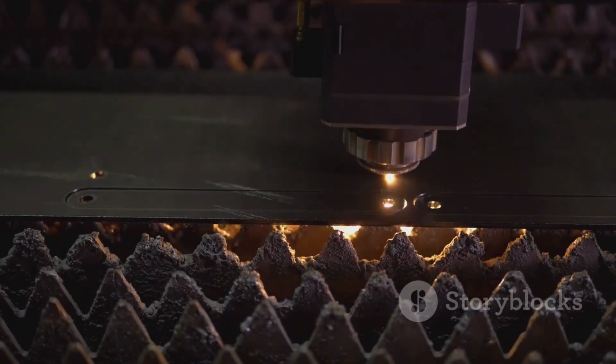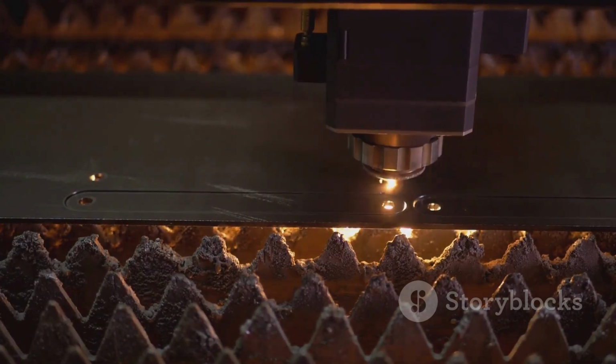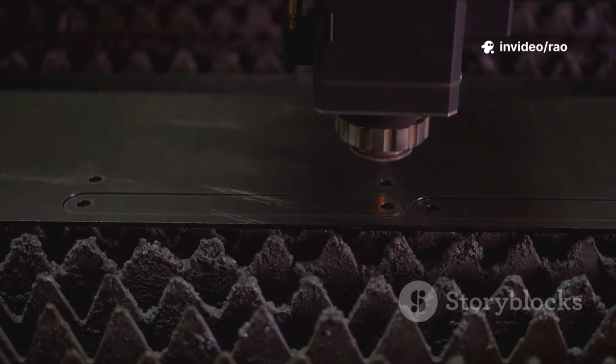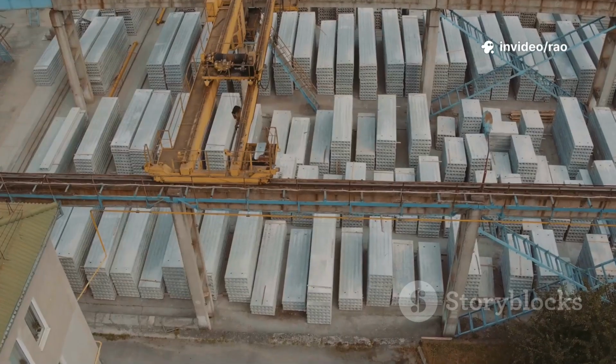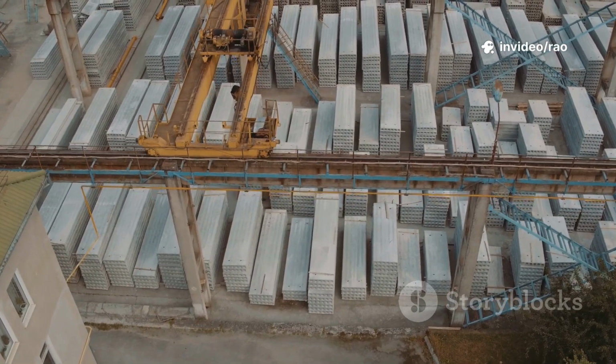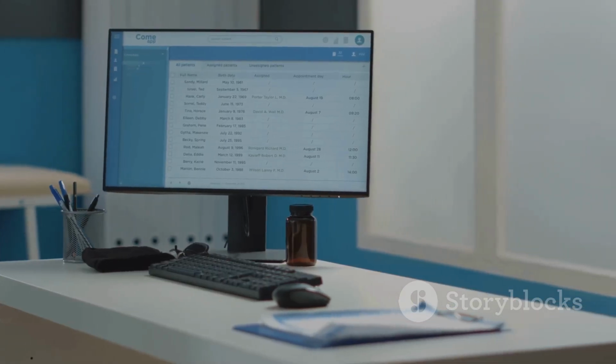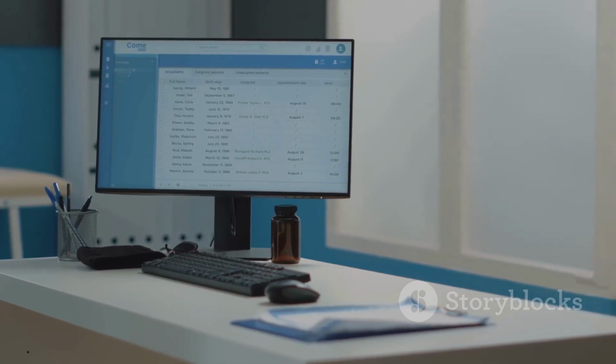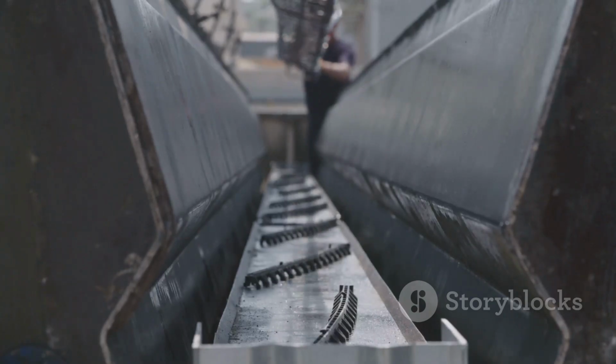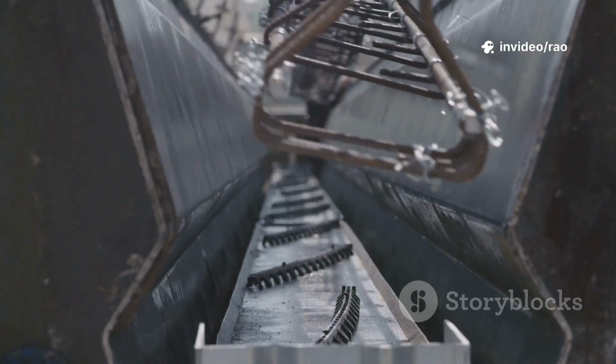This step highlights a common point of confusion. Remember, to count bars in one direction, use the perpendicular slab dimension. Visualize the slab. Number of bars: how many fit side by side across the width or length? This gives the basis for total steel length and avoids ordering errors. An incorrect count here will cause a shortage or a surplus of steel on site.